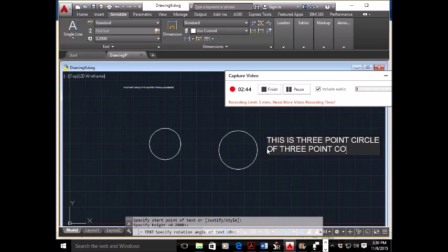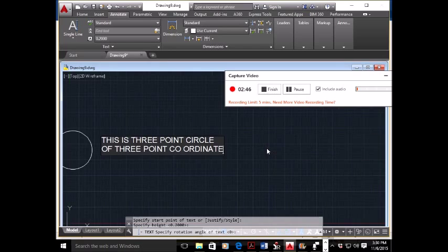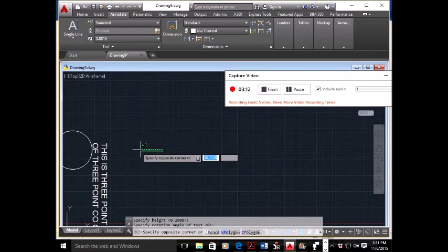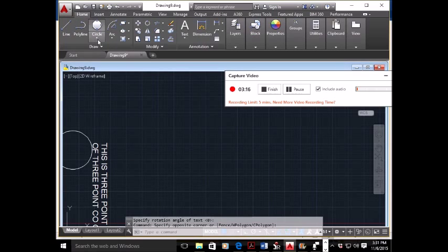Click Home tab, Annotation panel, Multi-line text. Specify opposite corners of a bounding box to define the width of the multi-line text object. If the ribbon is active, the Text Ribbon Contextual tab displays. If the ribbon is not active, the in-place text editor is displayed. To indent the first line of each paragraph, drag the first line indent slider on the ruler. To indent the other lines of each paragraph, drag the paragraph slider. To set tabs, click the ruler where you want a tab stop.